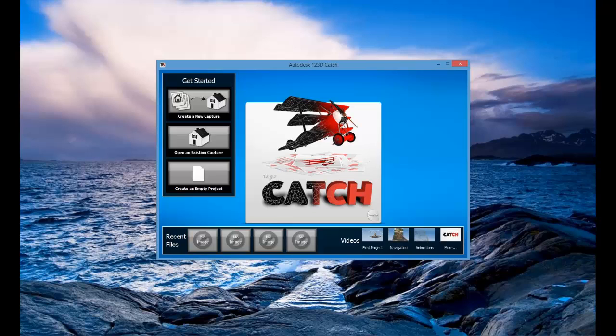The secret to ensuring that an accurate digital model of an object is created is to have a suitable environment to take the photographs in. The capture environment is essential to the success of capturing the target object. Factors such as the characteristics of the room, light, quality of camera used, technique used to take the photographs, and of course the type of object being captured all contribute to the success of the capture.